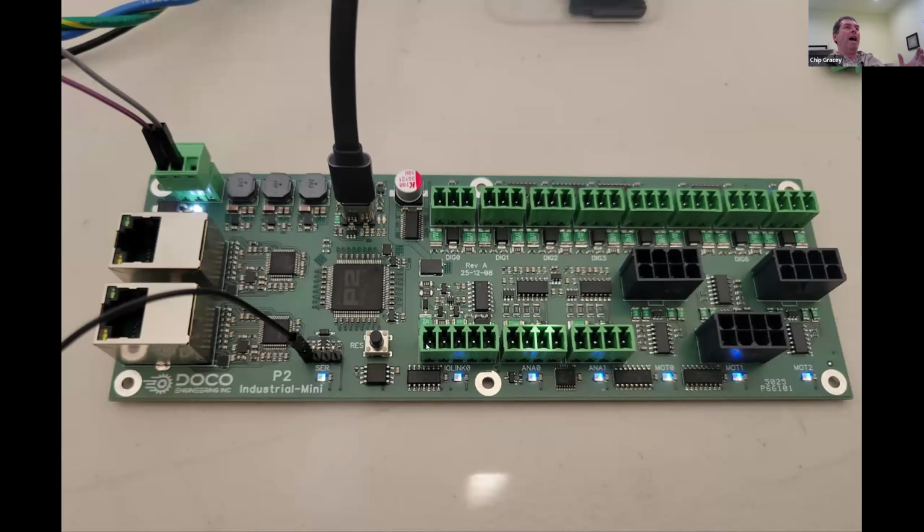And then for the actuator load, we have separate ground and 24 volts, because in industrial environments you have lots of wiring involved. When you're running higher currents to run actuators and stuff, you have significant voltage drop over those wires. So you need separate leads for the control circuitry and the load circuitry, which might be umpteen watts. So there's a lot of duplicated wiring in these bigger systems, which you wouldn't see in small electronics, because you have to accommodate all these voltage drops that can occur on higher current loads.